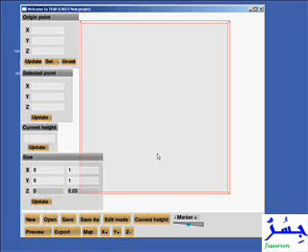When you're creating a topo data, one of the things that you would have to enter initially is the actual size in the X and in the Y area, and you would have to set those right here by clicking in the size box, setting your X and Y. You don't have to set the Z value. You'll be setting that as you are entering the topo data, which would be the dialog box above that, which is current height.